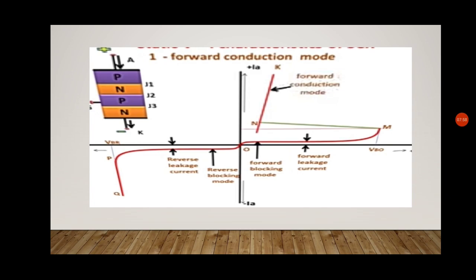Now we have to keep in mind, in both the cases, that we should not keep on increasing voltage beyond this VBO and VBR, as then there will be heating, a temperature increase in the SCR, which can burn it out.